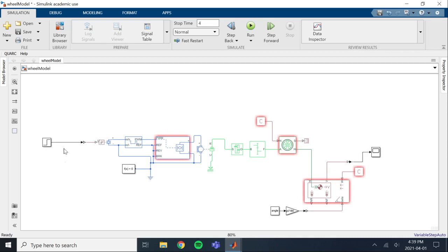So what I actually want now is to be able to specify the duty cycle that we are sending through our microcontroller as an input to the system. I want to see what happens when I change our input duty cycle, how that affects the movement of the rover. So what I'm going to do here is make a gain block.